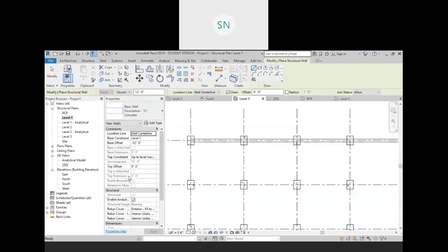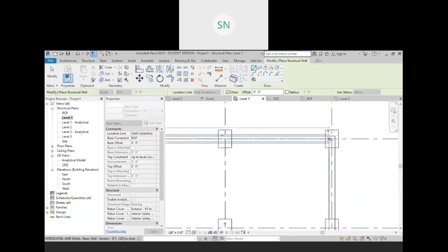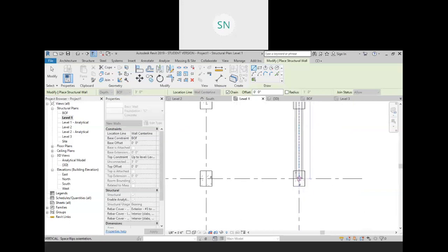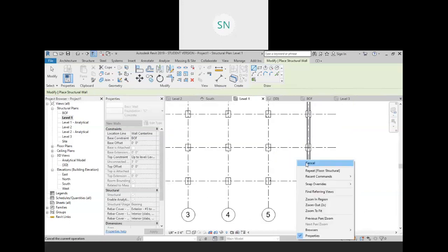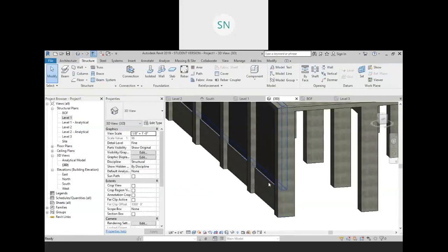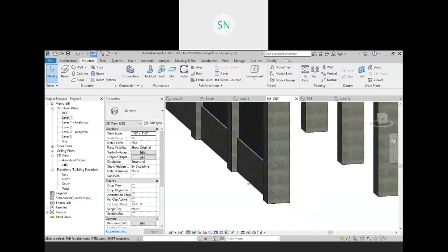Okay, thank you. So here we have chosen a 12-inch foundation concrete wall, right? And this time I will go into the depth, and I want to reach up to the bottom of foundation, and I'm going to create it from here to this point and up to this point. So these are the object creation tools we have, right? So this is my wall foundation.